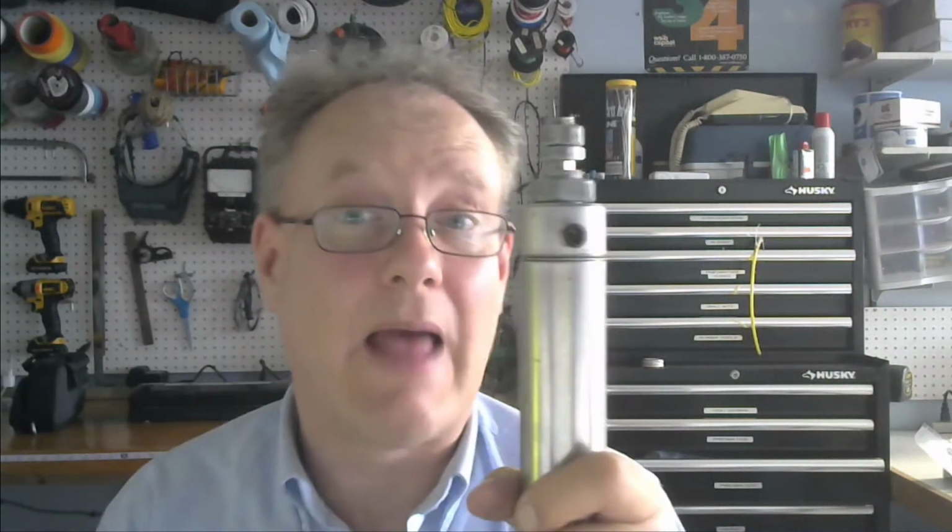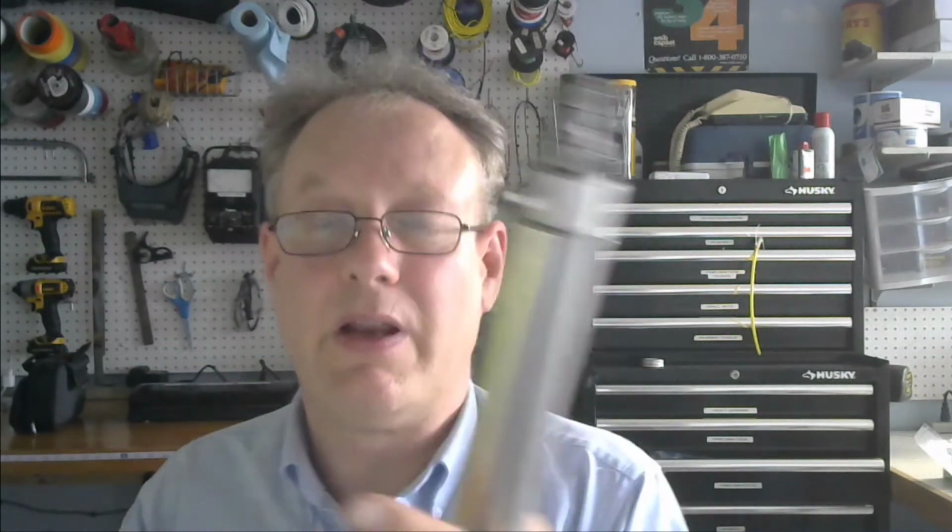If there is actually a load on my pneumatic cylinder, it's okay to meter in, but it's just generally not a good practice. And you will see, you can play around with it in the lab. You can actually change metering in and metering out. And you can see there's more control of the speed of a pneumatic actuator if you meter out. Let's talk about why we wouldn't meter in if there's really very little load.